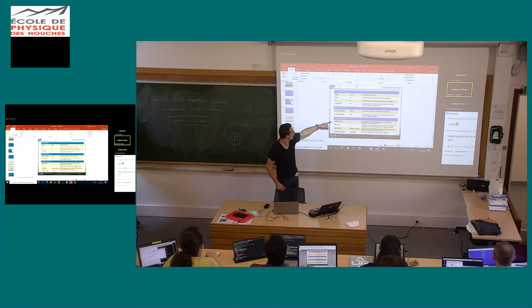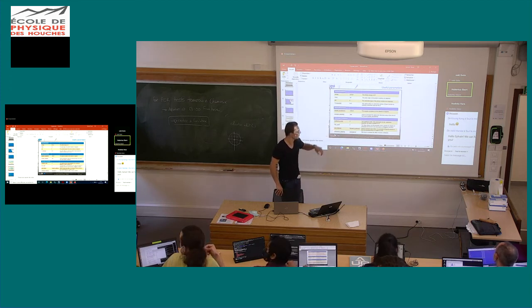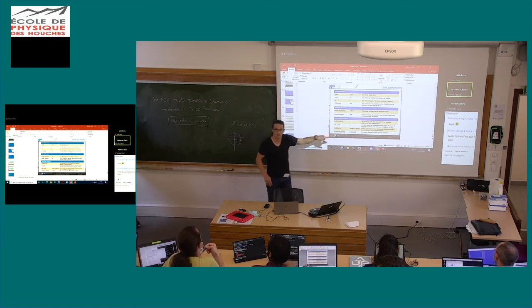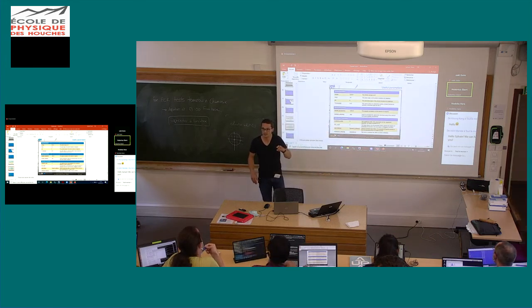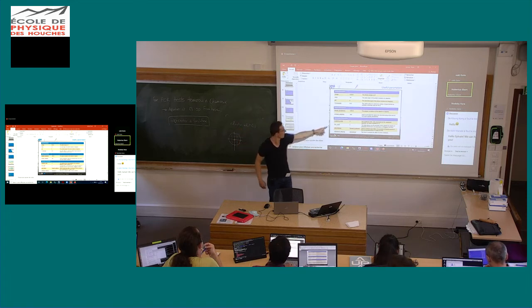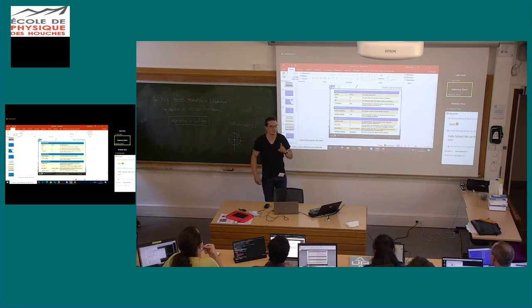Okay? And for the calculation parameters, there are many, but what we will be using today, and most of the time, you will have to control the scattering order, which is only relevant if you use the series expansion algorithm. It means how many scattering events you will consider for a photoelectron. By default, this is 3. It is limited to 10, but honestly, above 6, it begins to be very, very long for a calculation.